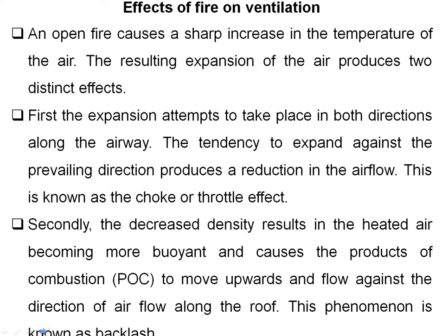So, effects of fire on ventilation, this is the most important slide, please note this down. An open fire causes a sharp increase in the temperature of the air. You know that if there is a fire, then there is obviously an increase in temperature, and the resulting expansion of the air produces two distinct effects. First of all, the expansion takes place in both directions along the airway, as it will spread through the airways, both intake and return. The tendency to expand against the prevailing direction produces a reduction in the airflow. This is known as the choke or throttle effect.